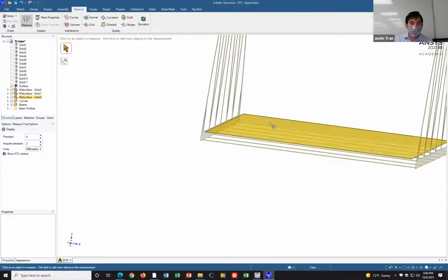All right, once you've loaded up into Ansys Mechanical, you should see your bridge in all of its flat glory. From here, the first thing we need to do is suppress this tiny little twig thing that I'm still not quite sure what it is. The nice thing is that it appears here as its own surface, so we're going to right click this and just suppress it. The name of that surface should just be sys/surface. We just went ahead and suppressed that.